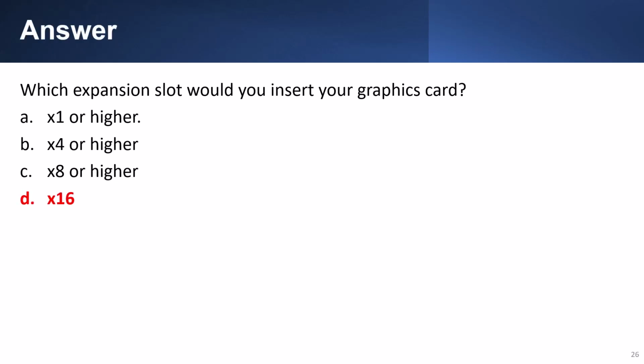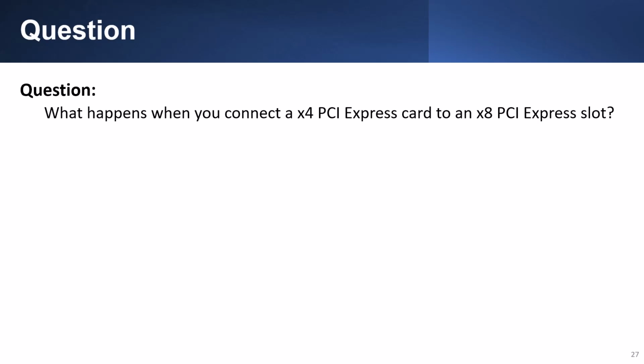Question: which expansion slot would you insert your graphics card? Answer: x16. Question: what happens when you connect a x4 PCI Express card to a x8 PCI Express slot? Answer: it runs at half the speed.